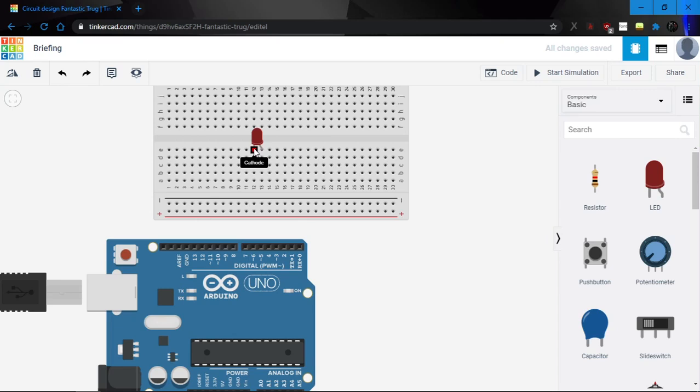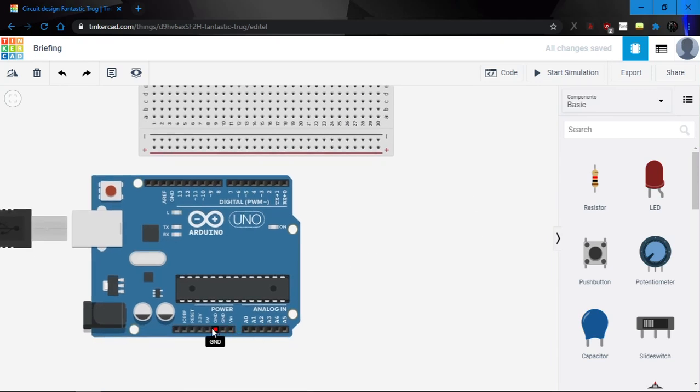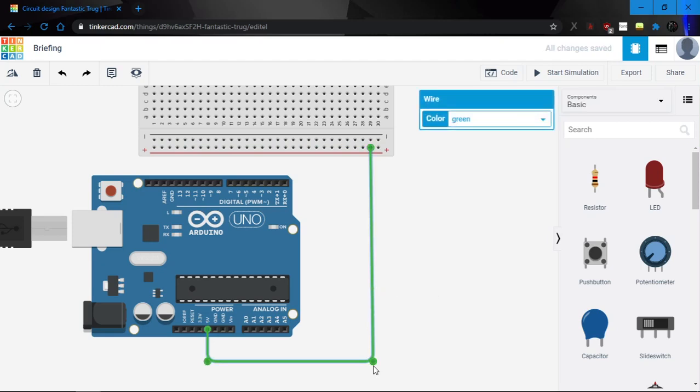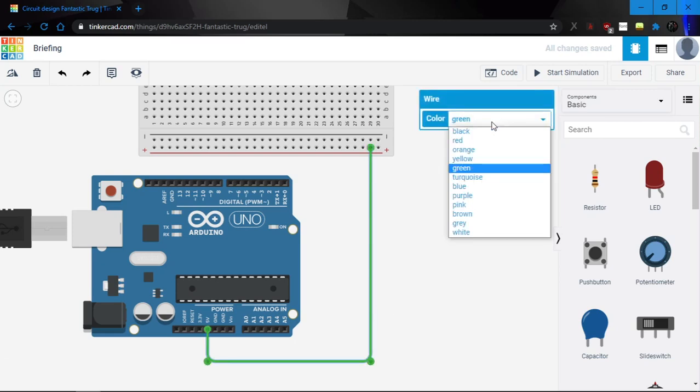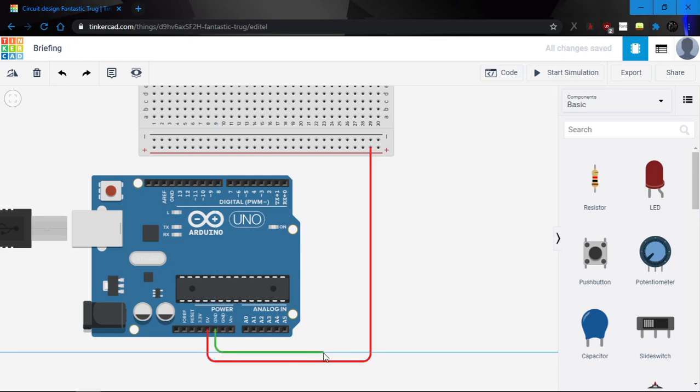Now for the wires, let's connect the wires. Once you press, you can connect the wire any way you want. To lock the wire or to make a turn, you just left click once. You can also adjust your wire by holding any point and dragging it anywhere. As you can see, the blue line indicates that my wire is at 90°. Every wire you put, you can also change the color. For 5V we use red, and for ground we use black.